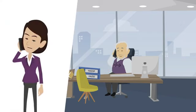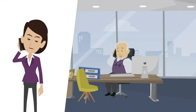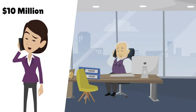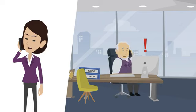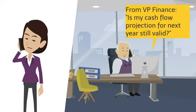Hey Ian, about the facility undergoing expansion due to increased input volume, we've done the calculation and it requires a flare upgrade to protect a new inlet pressure vessel from overpressure. How much would this cost and what kind of time delay are we looking at? The new flare has a price tag of $10 million and a schedule delay of 6 months. What is the risk of using the existing flare? Well, this risk is relatively low based on the HAZOP report. The only cause for overpressure is a control valve failing opposite of its fail-safe position. But I would still advise a full-size flare.